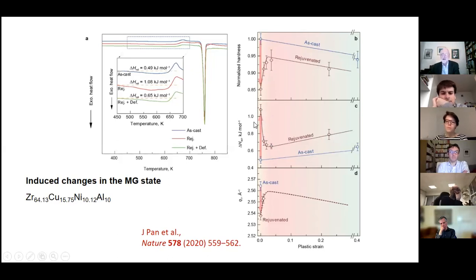So this is rather nice because this is real strain hardening, but it's absolutely the opposite of conventional Taylor hardening in polycrystals, in the sense that conventional hardening is to do with increased defect density, more dislocations. So conventional hardening is always associated with an increase in energy. This is associated with a decrease of energy. It's back to front in that sense.